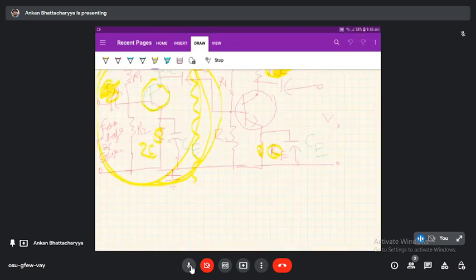Here lies the importance, and it is an important point that has to be noted here, that the total gain is less than the product of the gains of the individual stages. This is because when the second stage is used to follow the first stage, the effective load resistance of the first stage is reduced due to shunting effect of the input resistance of the second stage. Hence, in a multi-stage amplifier, only the gain of the last stage remains unchanged. This should be kept in mind.